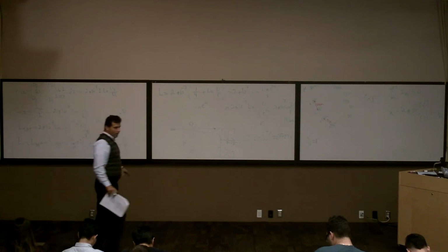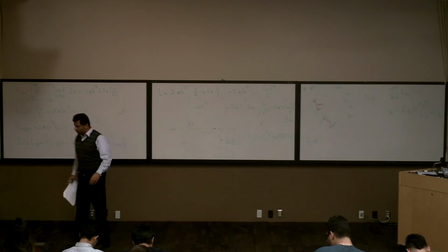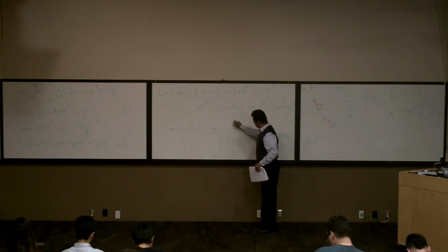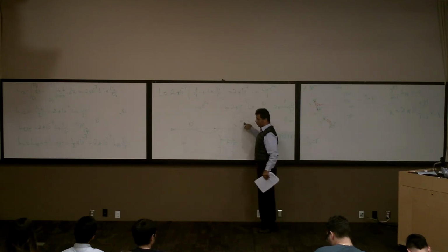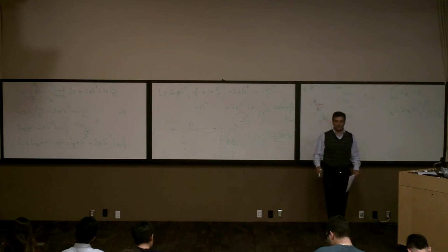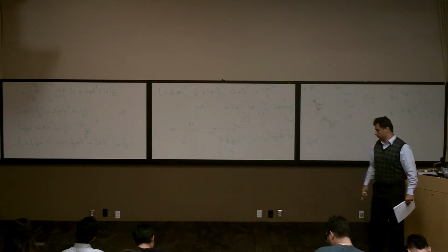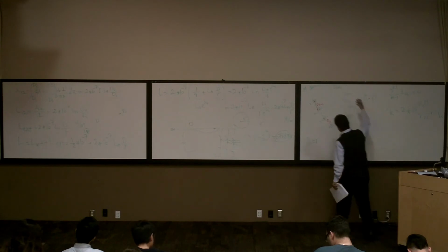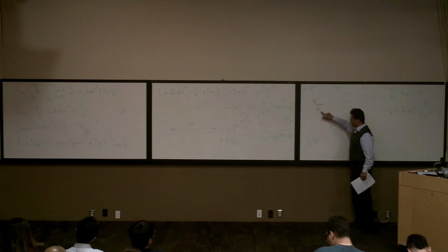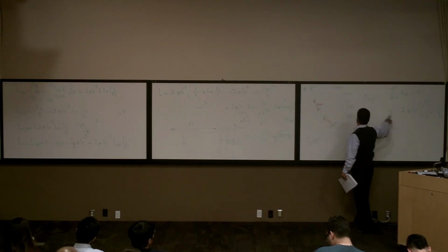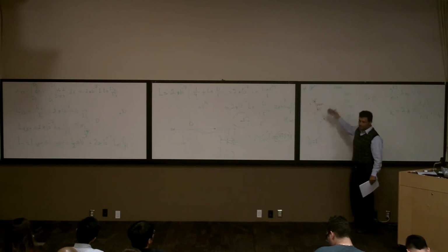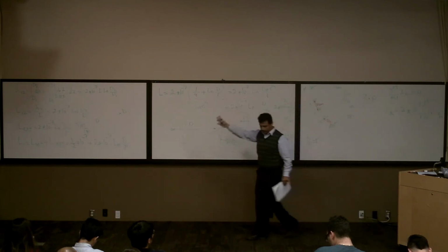Now, what is R prime? For a conductor with a radius of R, R prime is R times this number. 0.7788 R is the equivalent radius of this conductor. Now, if you have a multi-conductor system, the total flux linkage between this one and this one is calculated this way. If I want to calculate for this one, it's going to be lambda 2. Lambda 1, lambda 2, lambda 3, I can calculate all of them, right?